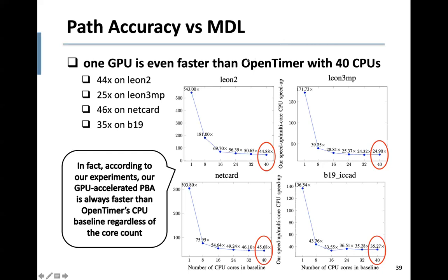No, indeed, that's one of the innovations in OpenTimer, because like you say, when we started working on this, one of the factors that affects the performance significantly is the load balancing. Because when you levelize this graph, you propagate the timing level by level, and even though you can run the timing in parallel for each level, you suffer from a lot of load balancing issues.